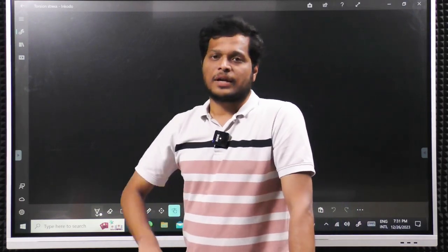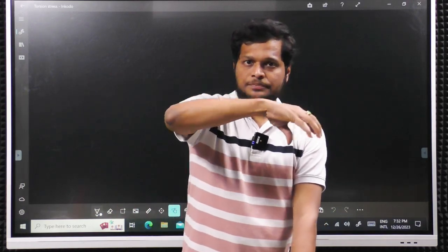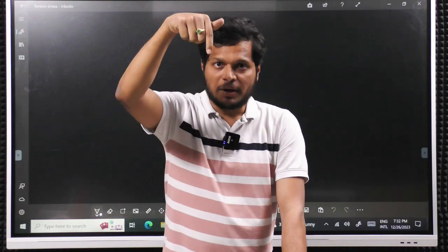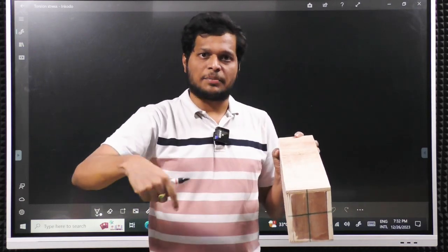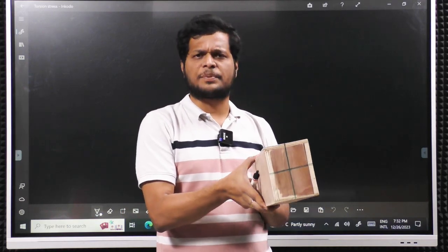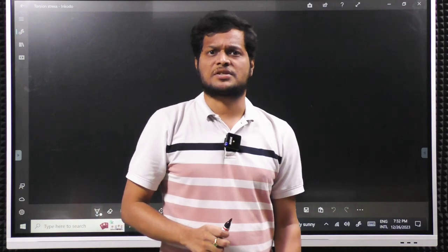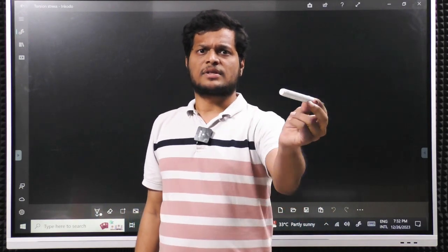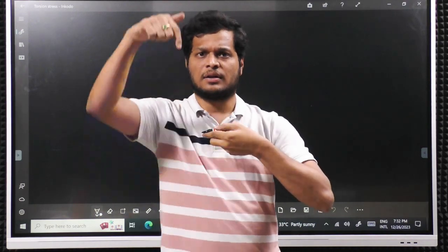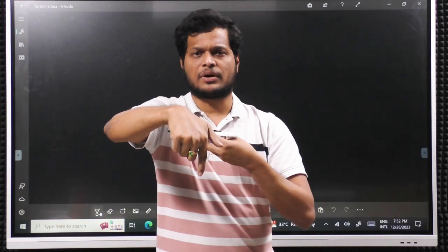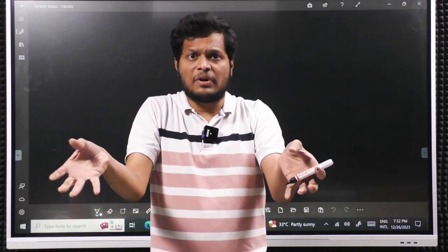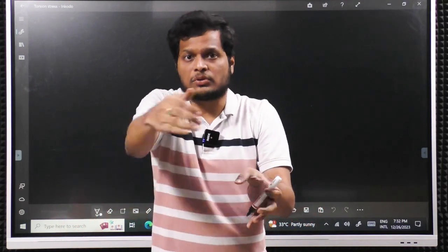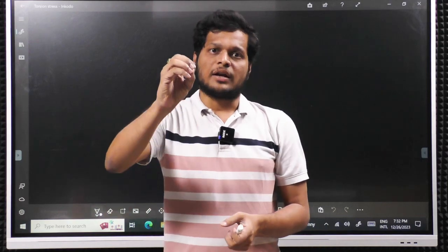Okay. One more example we can say is water tanks. In water tanks, we will be having ring beams. The water load coming at the center. So this ring beam, obviously it is not circle, it is ring beam. So for this ring beam, just like spring, at every point the longitudinal axis will change. Here the longitudinal axis is like this. So this is the longitudinal axis throughout the length. This is the load from the water because of gravity. So I can see the longitudinal axis is not meeting, not parallel. So the entire ring beam will twist like this because of the load. The entire beam through ring beam gets twisted.